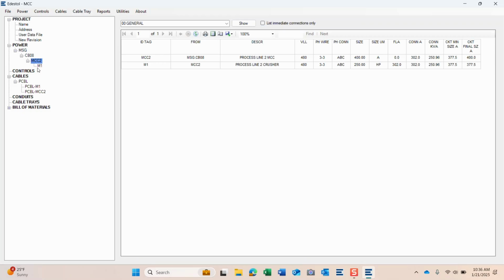Here's something about Motor Control Centers that's unique in this program. Obviously a Motor Control Center needs a starter to operate a motor, but we needed a way to add motors without knowing what the starters are. Typically you have a motor list, but you don't know whether they're adjustable speed or fixed, or whether you need a reduced voltage starter.